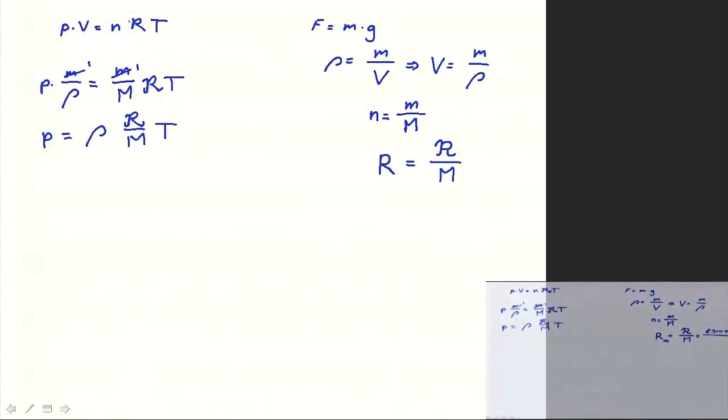Most of it is of course nitrogen, so it's very close to nitrogen. It's 28.97, which means the R that we will use most of the time is 287. This is gram per mole, so to be correct I should write it like this, and you should forget about the point there. This is easier for me to do than in your notes.